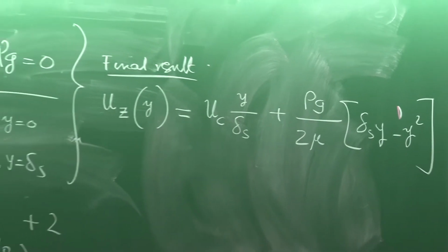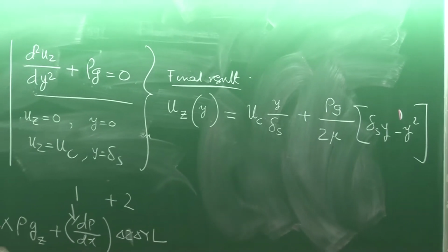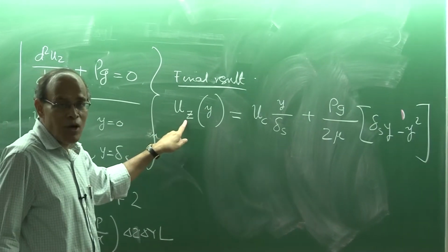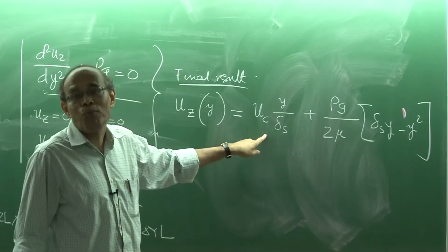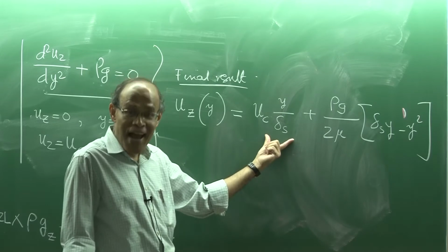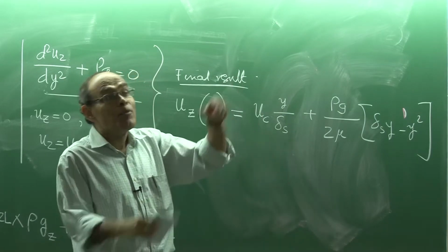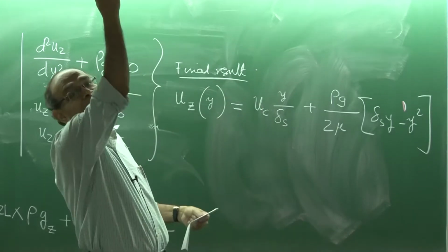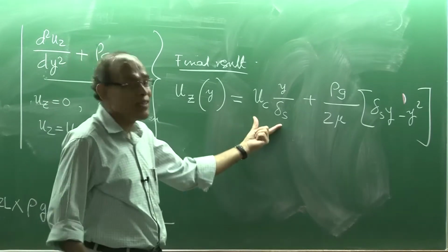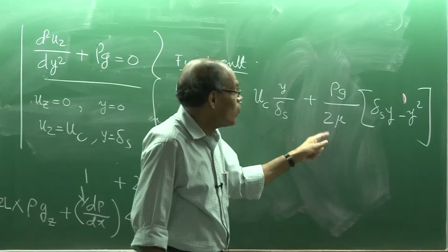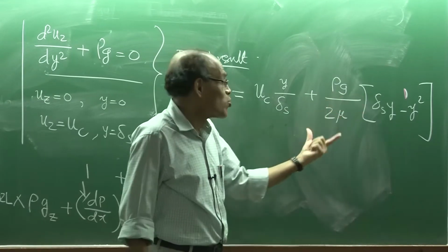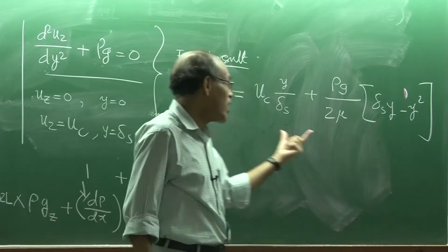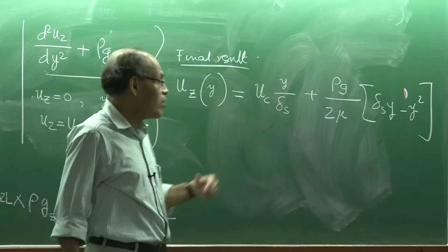which tells us that the flow of the film along the z direction is related to two different components. This comes from the drag effect, that is, because the strand is moving down, it is trying to drag fluid along with it, and it is also moving due to the gravity forces. So, the presence of g on this term. This is the gravitational component of the motion, and this is the drag component of the motion.